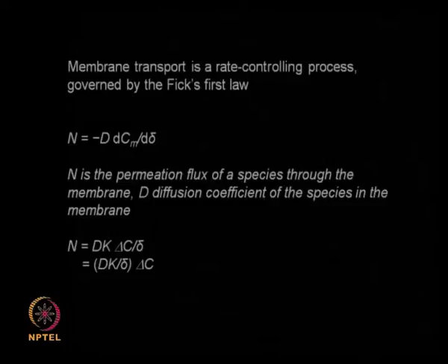Okay. Now membrane transport is a rate controlling process and it is given by Fick's law of diffusion. We all know what is Fick's law of diffusion. Fick's law of diffusion connects the flux with the driving force, that is the concentration gradient, and the diffusion coefficient, correct. So this is the Fick's law of diffusion. The permeation flux is equal to minus diffusion coefficient dC by d delta, that means this is the driving force and this is the distance.